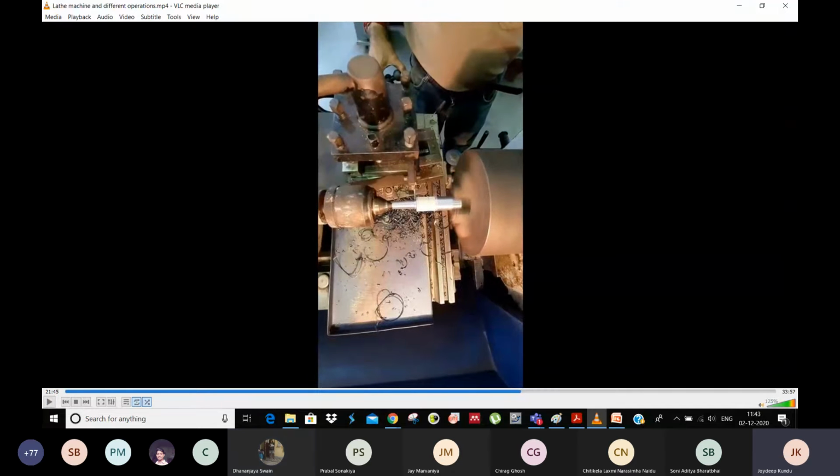So I guess your doubt is clear now. What would have happened if we had used the turning tool there? As already mentioned, there will be a taper. That means the slant edge will be there because the shape of the turning tool is like that. But in the case of the grooving tool, that shape is perfectly perpendicular. Sir, can't we do step turning? Then again, ultimately the finishing position will be of that slant edge. So even if you go for step turning, this problem will not be solved.